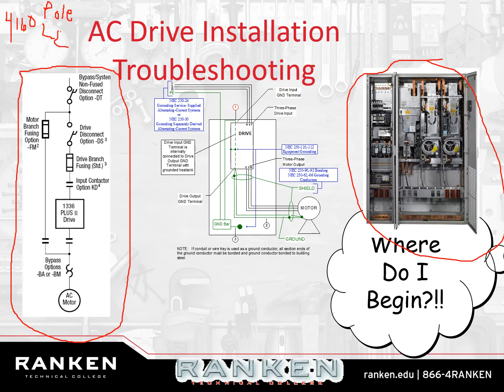I'm just going to put a box with a transformer. That transformer is going to drop it down to, usually, 480. But then ultimately it ends up down here at 208 volts, three-phase. In our shop, we have 208 volts, three-phase. So that comes into a disconnect. If you were in the upstairs shop, in the motors and drives shop, that disconnect would be the one that's powering the breaker panel. Let's just call it that.